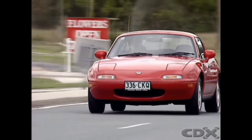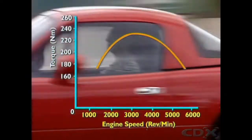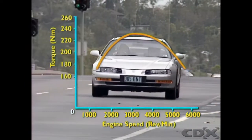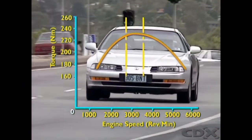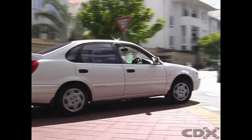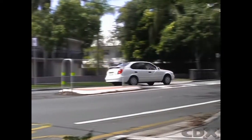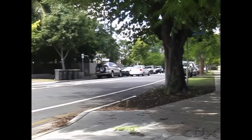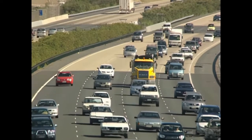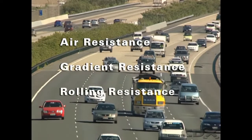In light vehicle applications, the engine operates over a wide speed range, but produces maximum torque only within a relatively narrow RPM band. A relatively large turning effort must be applied to the driving road wheels to move the vehicle. Then the turning effort must vary to overcome air and road resistance and rolling resistance.